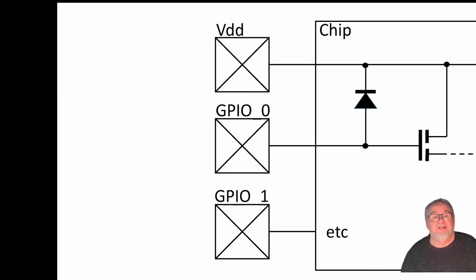And the chip reset itself and it reset the circuit. Because he neglected to connect the supply pin to the supply, the chip was getting supplied via its input pins. And there have actually been cases of people designing chips and using this as a design trick: we will supply it through the input pins. It's not something I would recommend, but it's something to know in case you ever come across it.